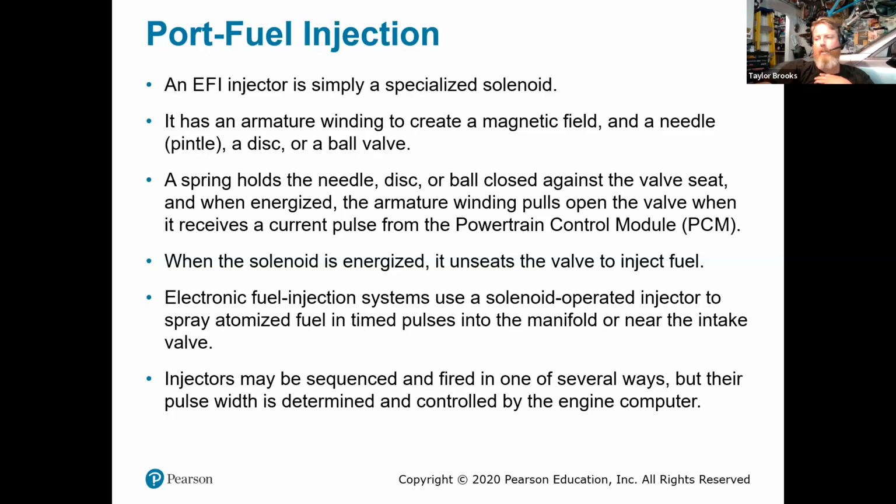denozzling fuel injectors. If you have a vehicle that you're trying to gain more power from, let's say you turbocharged or supercharged an engine that does not have fuel injectors readily available on the aftermarket with a higher pound rating, you would take the stock injectors out. Usually there is a shroud covering the needle and the pintle, and you would unshroud or open up the fuel injectors.